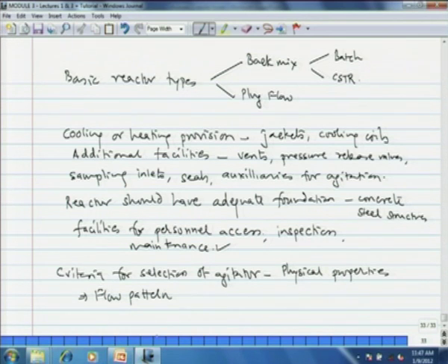In some cases, flow reactors have large cylinders through which the reactant flows, while others are designed in the form of multiple tubes located in parallel with the reactant flowing inside the tubes. In these cases, where the reactant is distributed in multiple tubes, you can assume the reactor operation to be ideal plug flow, because the extent of back mixing is very small. As the diameter of the flow increases, the extent of back mixing also increases. So that point we note here.